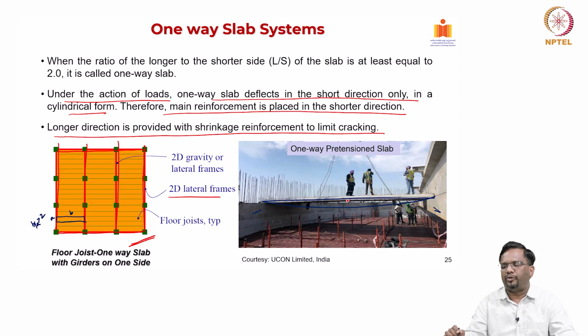Now, these slabs also can be either post-tensioned or pre-tensioned, but typically if these elements are made in factory, it is easy for us to do pre-tensioning, because I can make more number of products by going for a long line method of casting. So, such kind of elements are usually done using pre-tension, right. That can also be done. So, this is one-way slab. One-way slabs are pre-stressed, either post-tension or pre-tension, but if the slabs are made in factory, typically they are pre-tensioned, right.